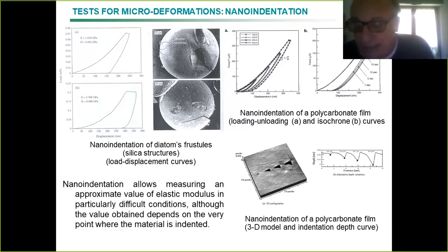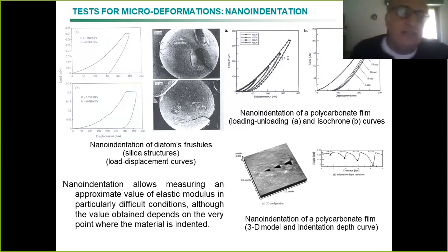After you have applied some strength, you can see here that we have a hysteresis. There is no really elastic behavior at this small dimension. There is always a kind of accommodation, a plastic behavior from the beginning, and in fact it is recognized by this kind of curve, which results in a hysteresis, so in sparing some energy.